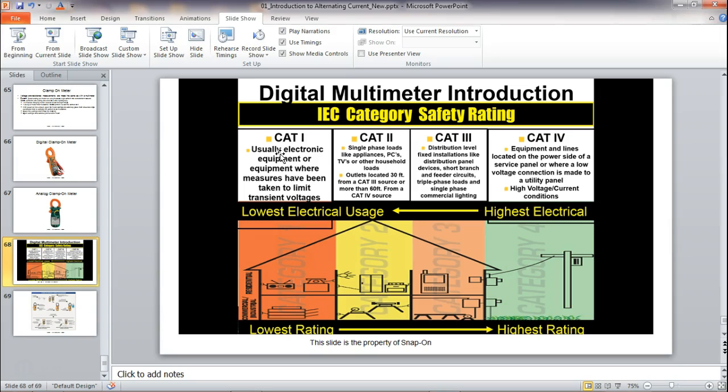Well, that's going to create, and the regulators way back at the plant that it comes from don't see that way down the line, a voltage spike. So big old loads, or if a tree branch drops across a power line and causes them to touch and then it bounces back up, this causes voltage spikes to move down the line.